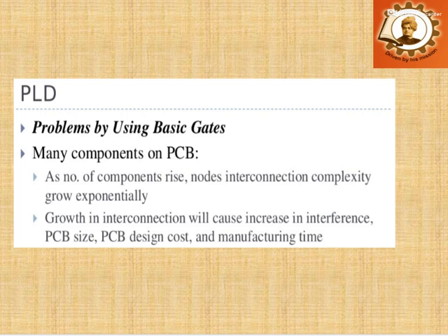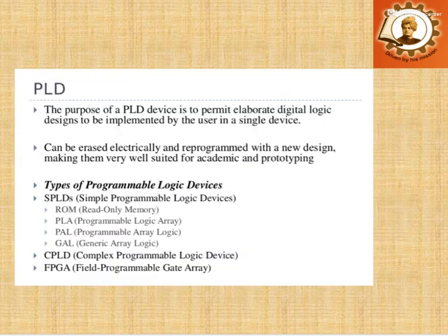So here logic devices are divided into three types. One is called SPLD, simple programmable logic device, which is divided into different categories like ROM, PLA (programmable logic array) and PAL (programmable array logic). The other types of logic devices are CPLD and FPGA.